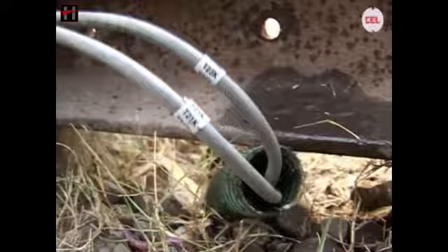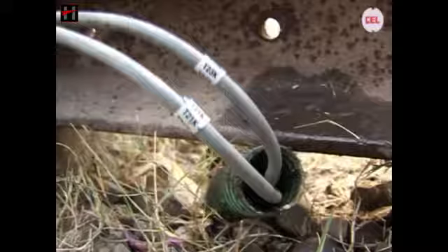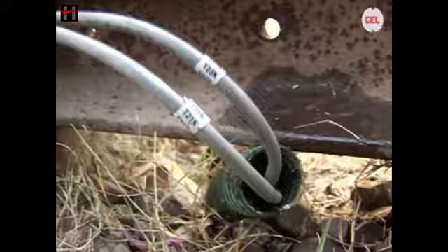Take the TX coil cables marked with 21 kHz and 23 kHz together in one HDPE pipe to the location box. Similarly, take both RX coils marked with 21 kHz and 23 kHz together in a separate HDPE pipe to the location box.